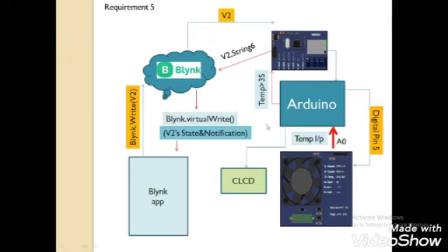So if the temperature is greater than 35, we have to turn off the heater. We are taking temperature values via A0, that is the input, and giving them to the Arduino Uno A0. We send temperature values to the Arduino Uno, and if the temperature is greater than 35, we send that data via the Ethernet shield, and here we are using 2 virtual pins.